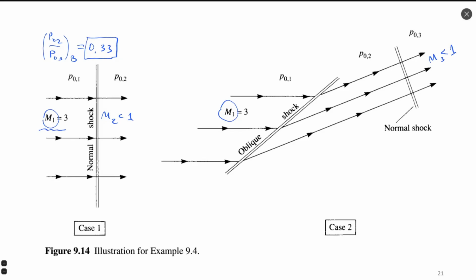What will happen in this case? In this case, we receive smaller efficiency, we receive smaller thrust, and we receive smaller flight velocity. We can say that a typical diffuser that works on just a normal shock wave flies at approximately Mach 1.5.